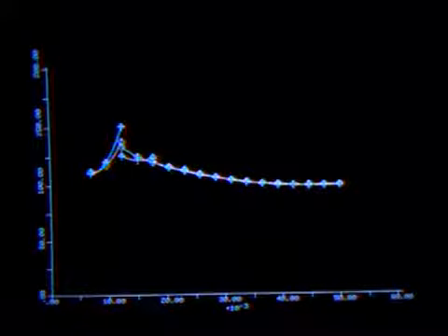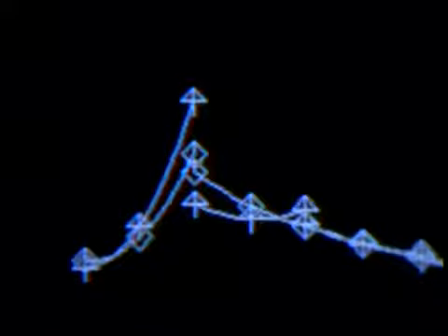Next, we look at the stress plot along the diagonal line of the model. Here, the maximum principal stress is plotted. Note that at one node into which 4 elements couple, we have 4 markedly different stress values. Indeed, we have significant stress jumps at that node, but otherwise the stress predictions do not show large jumps.